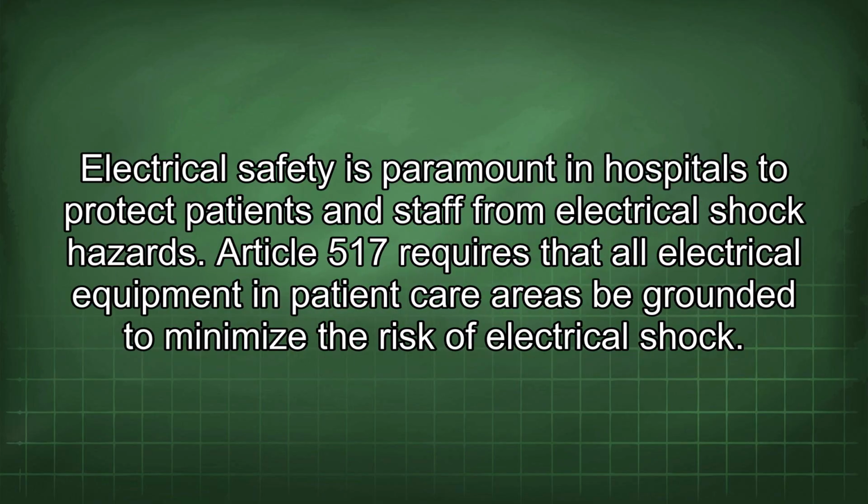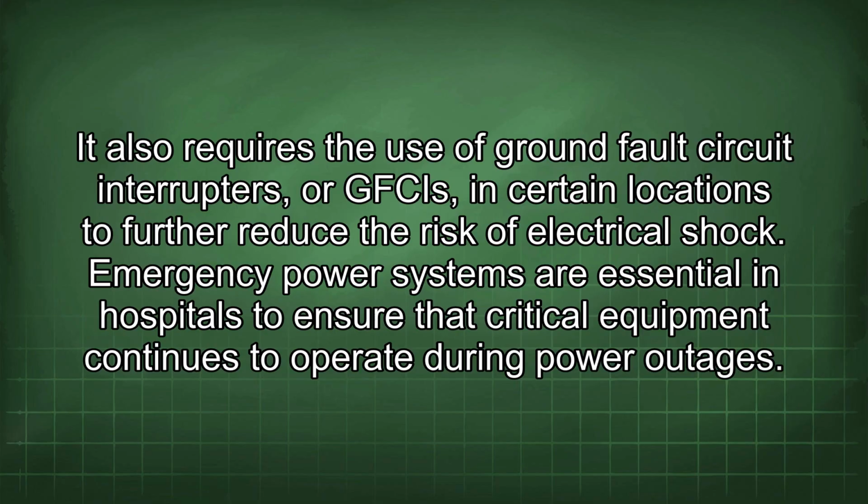Electrical safety is paramount in hospitals to protect patients and staff from electrical shock hazards. Article 517 requires that all electrical equipment in patient care areas be grounded to minimize the risk of electrical shock. It also requires the use of ground fault circuit interrupters, or GFCIs, in certain locations to further reduce the risk of electrical shock.